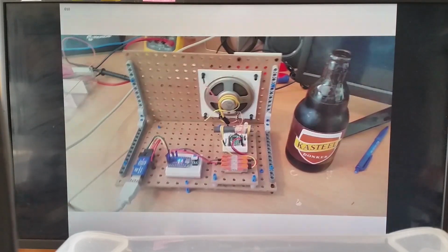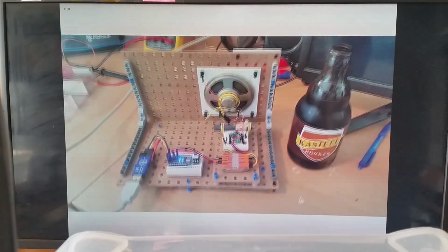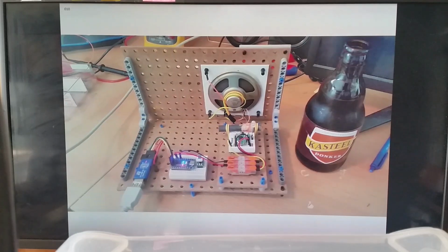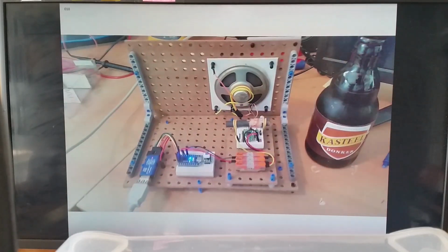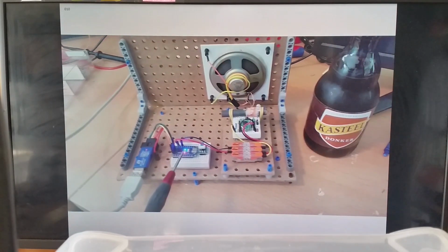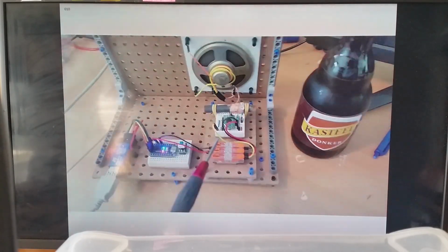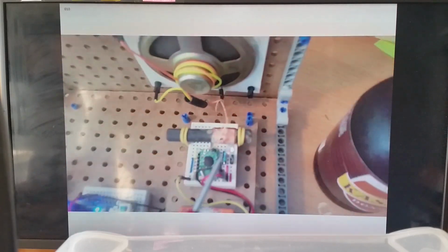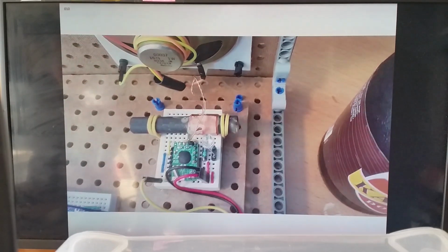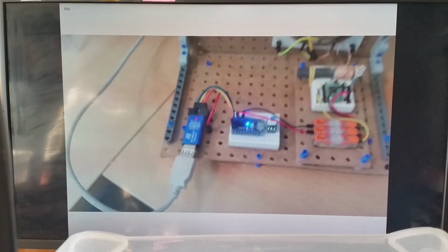Apologizing with the help of a beer, I dismantled a previous project about the FM receiver, and I created this one. The loudspeaker is not used, just there. Debugger programmer, STM8S103, an on-off switch is not needed anymore, and the DCF77 is powered by, you can see it blinking each second, it's powered by 3.3 volts from the programming interface.